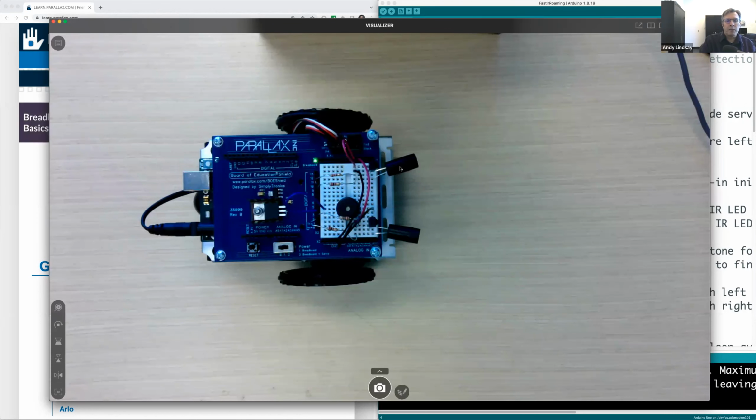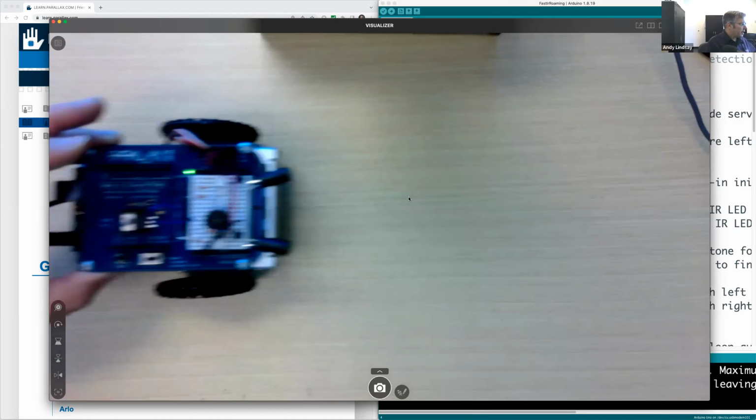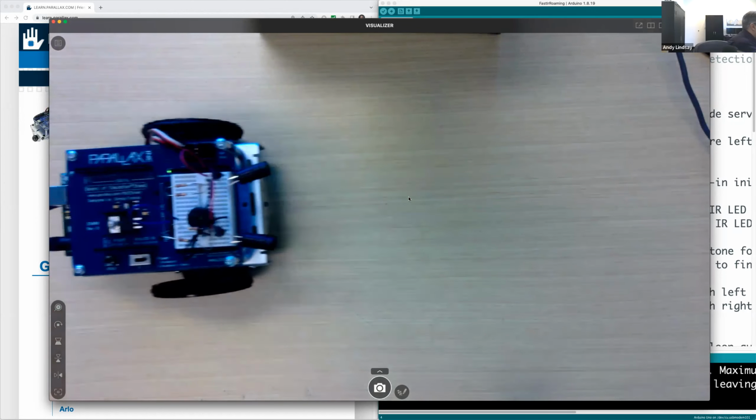With the infrared here, sure, it might see a slightly lower item, although you can't really get too low, but items that absorb infrared like vinyl electrical tape and the black, is it called Cove base, Stephanie? Yes. That is around the base of the floor and comes up about 6 inches on the wall in many schoolrooms, also is mostly invisible to infrared. So use an object like a cardboard box, which will reflect it pretty well. So here goes my robot, and I put my hand in front of it.